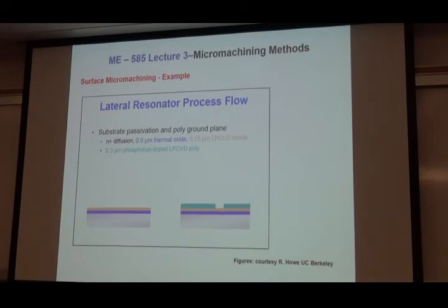To do a patterning, you have to deposit the photoresist. Then you bring the mask, and you cover everything else except this part. Then you come with a DRIE or a wet etching and etch that. And then eventually strip off the photoresist. So yeah, positive for example. At the end, you have poly 0, which is patterned.